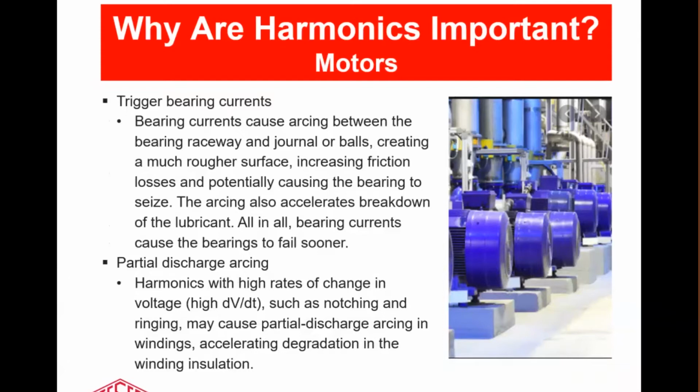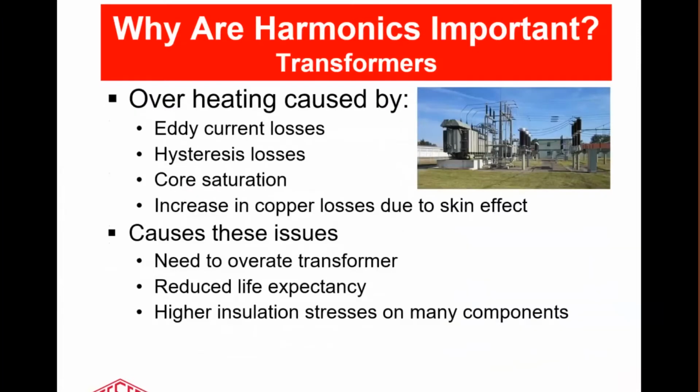If they're really high dV/dt kinds of harmonics, they can create notching and ringing type of harmonics that may appear in certain kinds of drives. They can cause partial discharge arcing, and again, degrade insulation and reduce the lifetime of the motor.